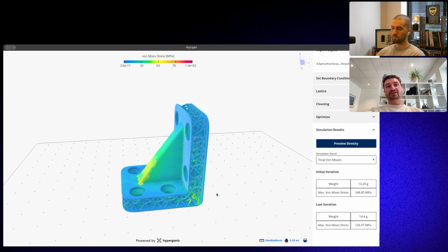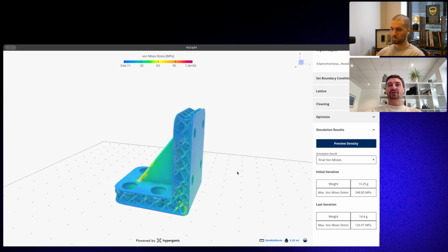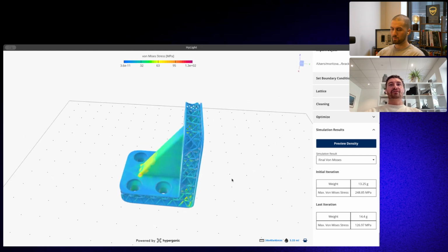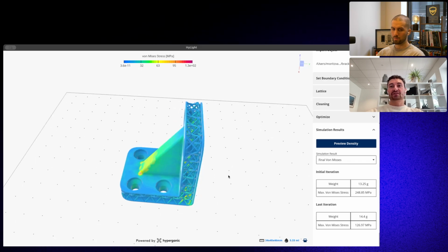One is to optimize beam lattices. So you start with a lattice structure that is too weak, and you iteratively increase the beam thickness in the areas of highest stress, so that the bracket overall becomes stiffer. The other version is to leverage field-driven TPMS design, where you use TPMSs or implicit fields to fill the space and then grade or modulate these TPMSs according to the simulation field. What that looks like, I'll of course show in just a second.